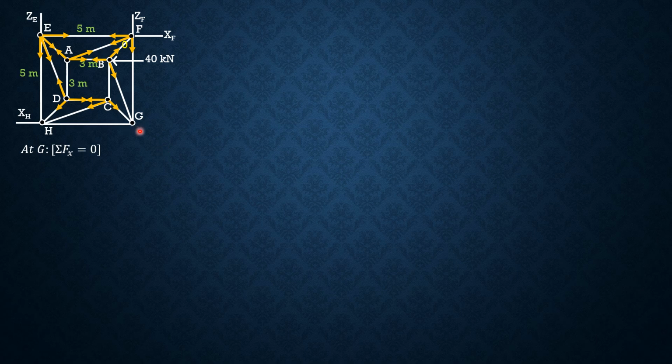So since everything is going to the left, let's consider going to the left as positive. Remember that BG is 0, so SCG is found in the preceding slides, and SFG is also found. So summation forces X equals 0, leftward positive, SGH plus SCG. SCG was negative 13.27 times 1 over square root of 11, then no more equals 0. So SGH is equal to 4 kilonewtons tension.